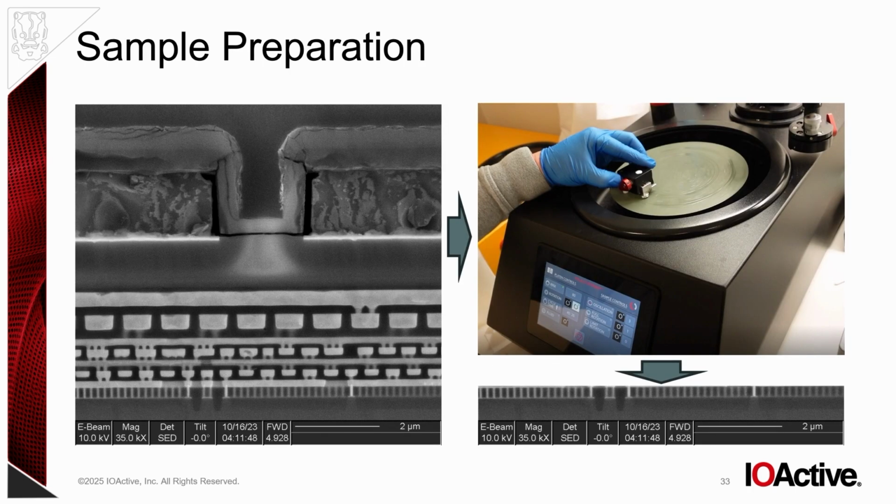So we need to get down to the fuses or near the fuses to try and play around with this technique. So what we do is we use something that looks a bit Dickensian there, but it's a polishing wheel. And it's a quick and easy way to deprocess chips if you have some skills. And it's not easy, I can tell you. But if you've got some time and some motivation with something like that, I mean, that's like a $25,000 instrument there.